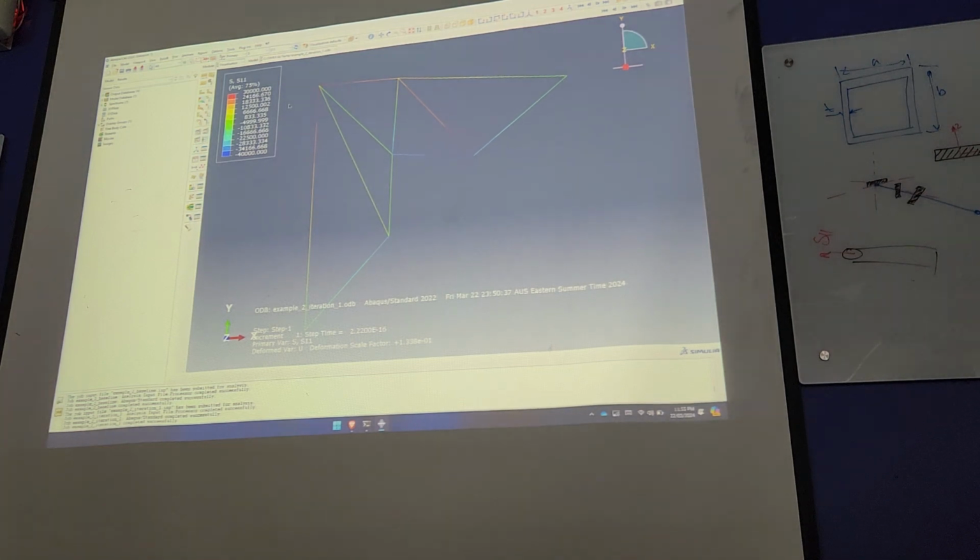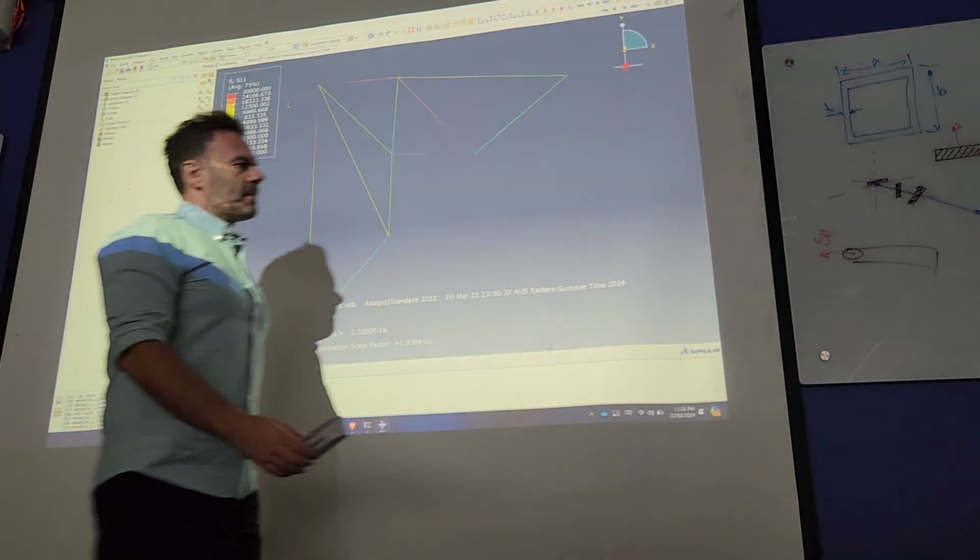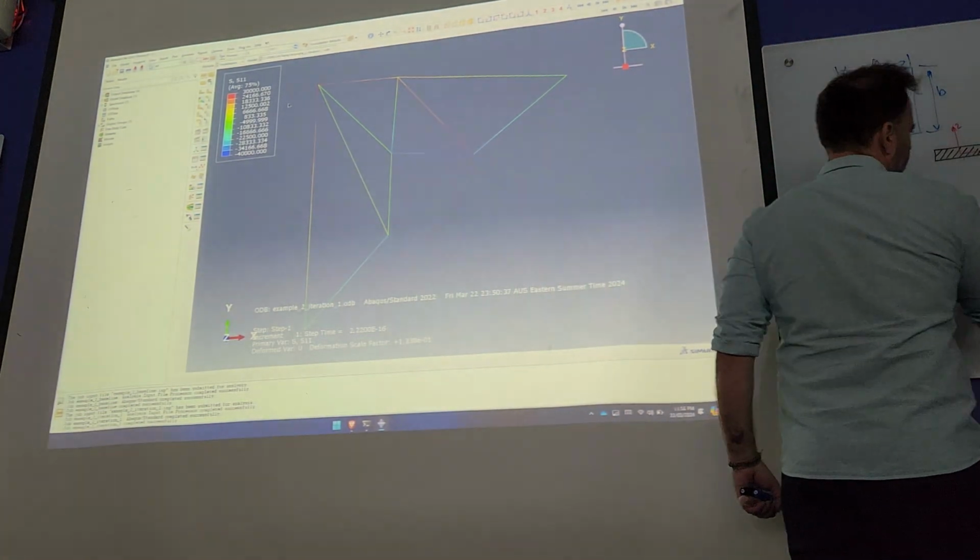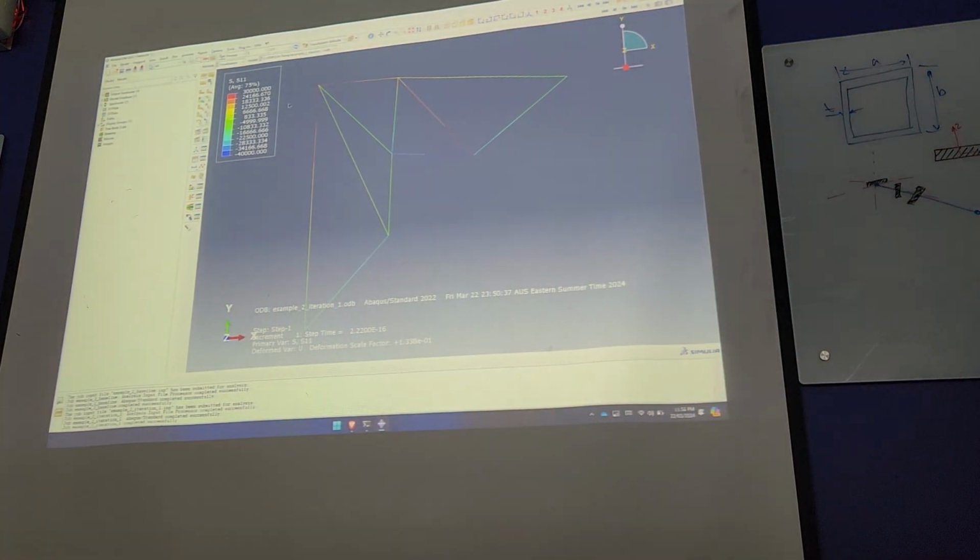But your this one is quite balanced because of grade one, but if you want you can change, you can make another property, you go to property. Then you can reassign. So your first challenge is to sort out the stress. You got this section where you create, then you make a thicker cross section. Not so thick, a bit thicker than what you have. Then after that what you do is close, right?